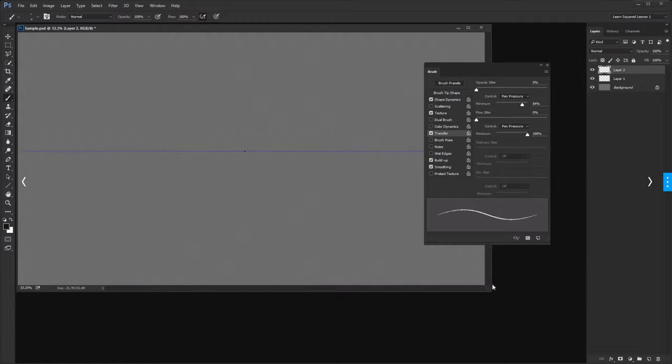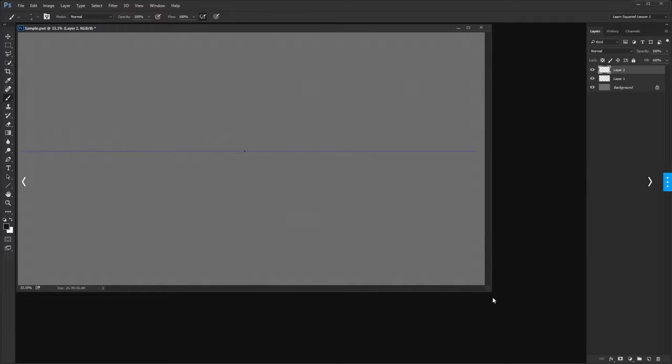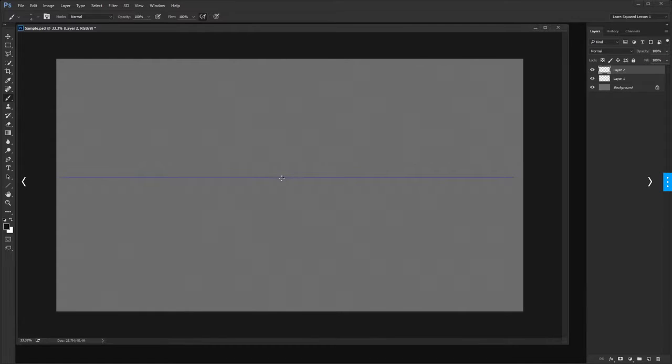So let's go from here. Let's go ahead and draw the line. So I'll click, hold shift, and then click again. You can also just draw the line like this, and you can make a couple of tries, and I'm drawing from elbow when I'm doing those. But it becomes trickier and trickier when you do that. So holding shift will make sure that the line is straight.